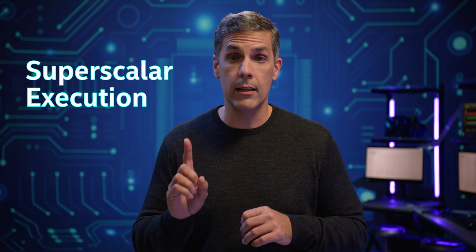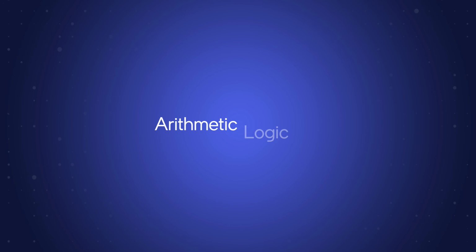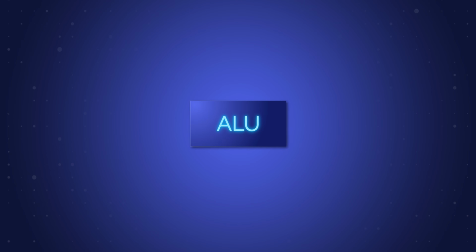Before we dive into how the back end of a microprocessor is built, let's take a moment to understand two important topics. The first is superscalar execution. The simplest form of execution is an arithmetic logic unit, or ALU for short. A basic ALU can perform operations like adds and subtracts.